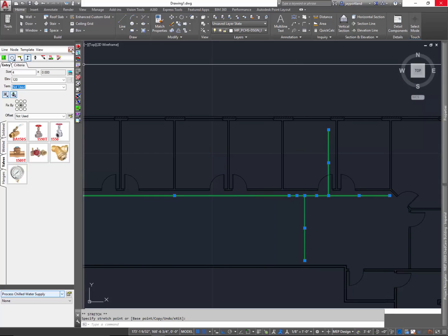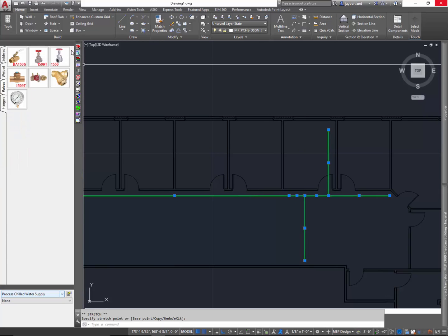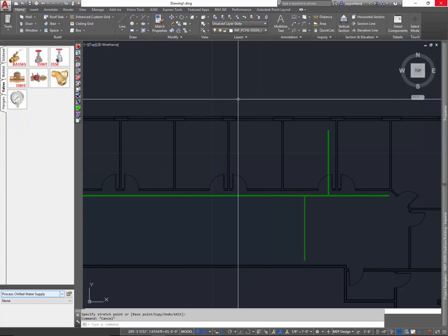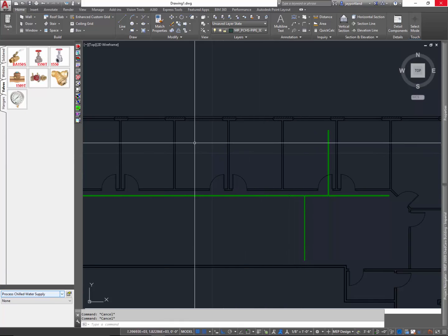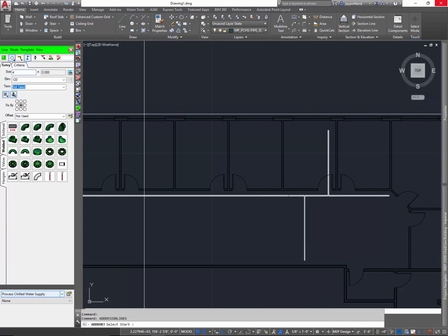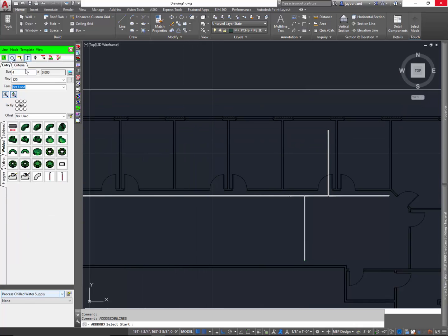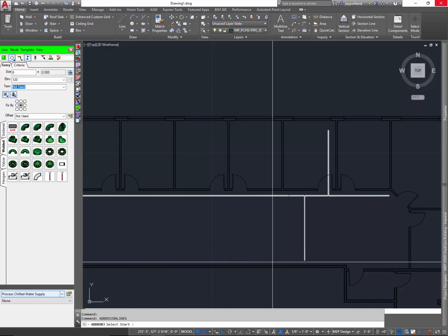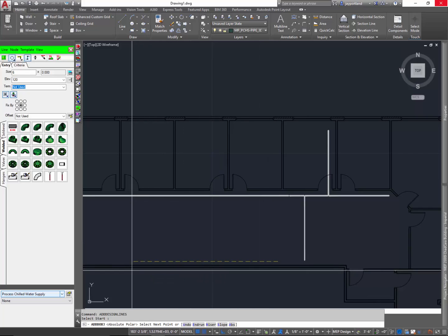Now, if you click on the red X button here during the design line editing phase, what it does is it closes out that design line. And if you click on the design line again, it'll kick off the design line feature, right? So now I'm dealing with a different design line totally at 6 inches. I can start working my way backwards in this direction.